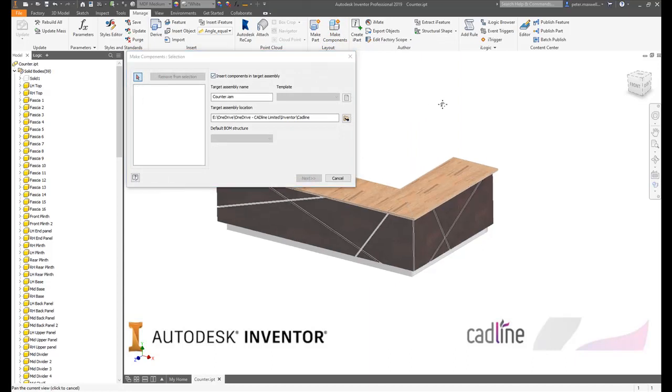From there you can see we can assign an assembly name or place it into an existing assembly. Here, because I have an existing assembly called counter, the template function is disabled, and this will place it into that assembly. If I want it to be its own unique one, I'll call it counter for nesting, put 2 on, and you see it's creating its own assembly.